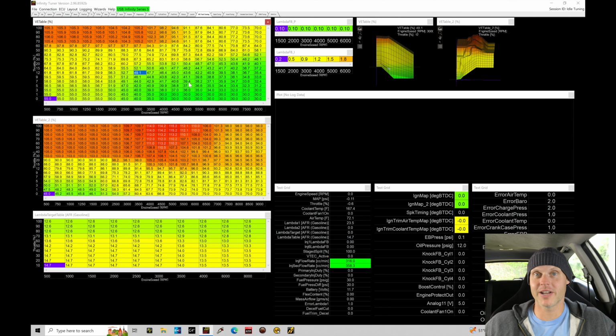Welcome back to our live training session. We're going to be taking a look in this tutorial at how to dial in our part throttle calibration process in an alpha-N strategy with our individual throttle bodies. This process is pretty straightforward. It's very similar to what we've already covered in other live training tutorials, but it is a little bit different because we now have throttle position as the load input to our main VE table.